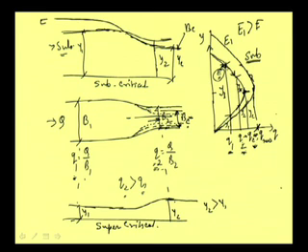This rise will make the energy level increase here, say energy level will be E1. Earlier the energy level at this point was E, here it will be E1, and this high energy level will push the water, but the depth here will remain critical again. So, we are getting critical depth here again, but between this critical depth and this critical depth there is a difference, but we are getting critical depth here.